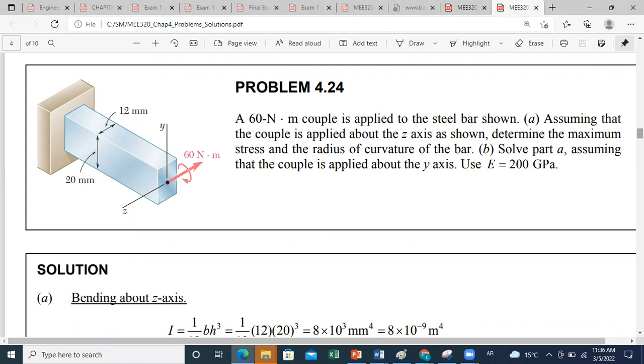So as you can see here, the bending moment vector is a vector along the cross section. It can be along y, it can be along z. Okay, in both cases, you will create bending. Because the condition for bending is that the vector bending moment will be within the section of your cross section.